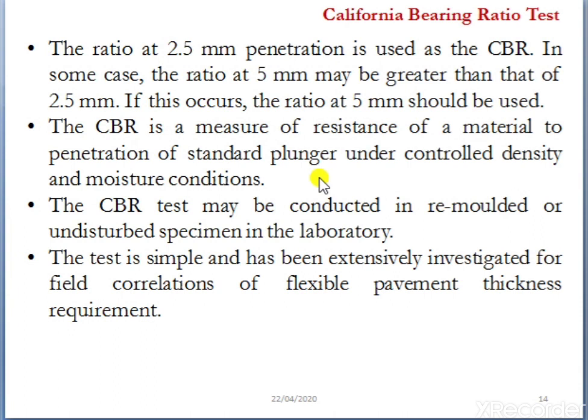The CBR test may be conducted on a remolded or undisturbed specimen in the laboratory. So we can determine the CBR value of a sample in two cases: one is in remolded condition, or in an undisturbed specimen in the laboratory. This depends upon the importance and requirement of the project.